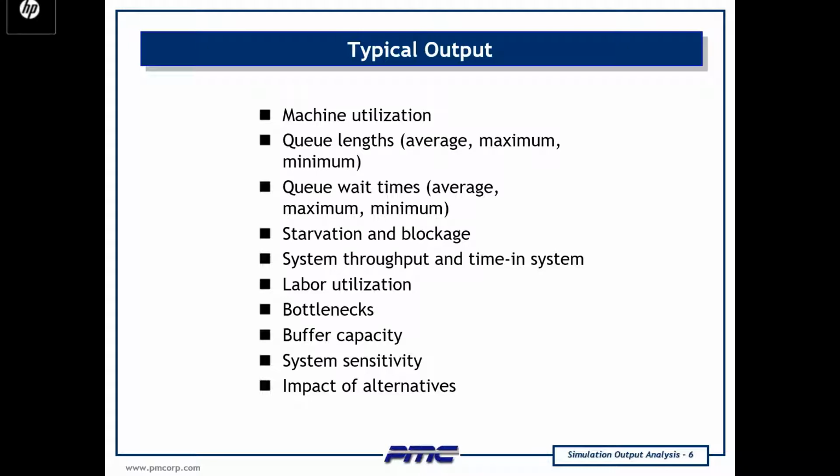Starvation and blockage are two heads of the same hydra. Starvation means a machine or a person is ready to work, but has nothing to do. There's trouble upstream, like an inventory shortage or a machine that went down. And upstream, the machine that has nowhere to put its output because the next machine is down or overutilized, it is blocked and hence can take on no more work.